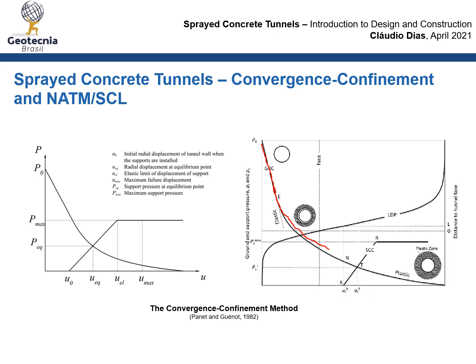So at the moment we arrive with the tunnel face to this region of the ground, it's very important to install a stiff support as soon as possible. That's why it's so important to use a material such as shotcrete to make sure we have a stiff early age strength, and the sooner we install it, the better, to make sure you maintain the properties of the surrounding ground and to use the surrounding ground as part of the support system.